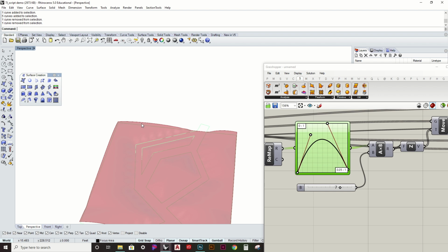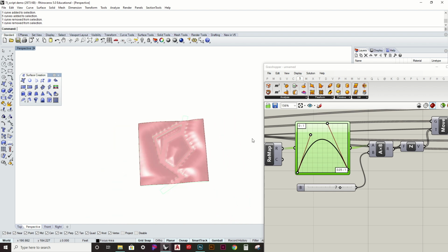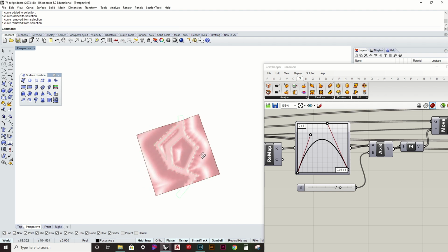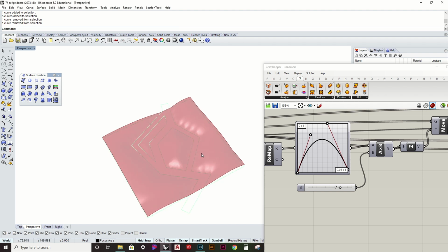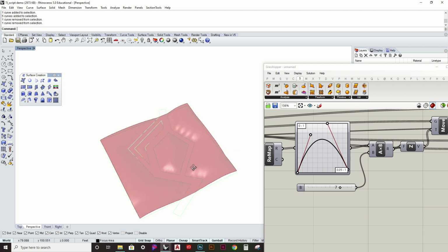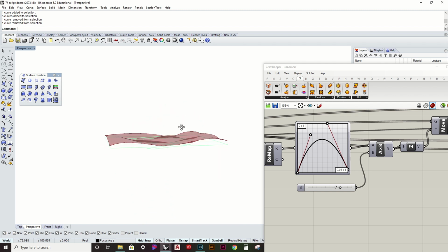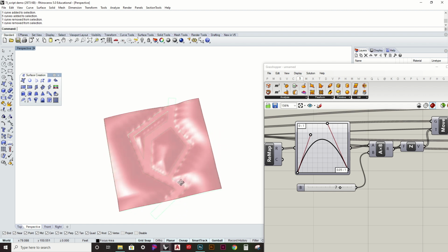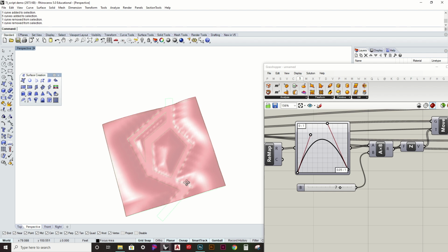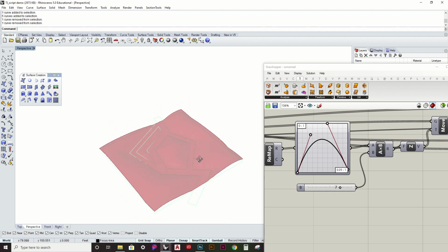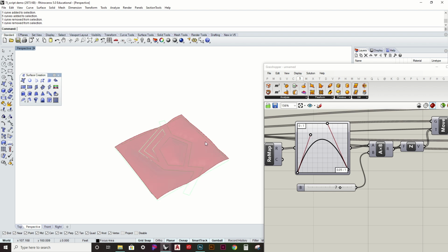So another kind of fun way where you dictate your path and have the landforms respond to it versus the other process that we'll show in the next video of starting with your landform that you've created and having your pathway respond to it to fulfill those parameters of a 0 to 5% slope. So, yep, there you go.